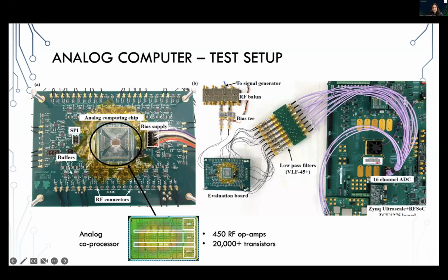And we are using an external signal generator or external supply. We can provide an input signal to this analog chip, and it then produces analog outputs. Those outputs are converted using analog to digital converters into the digital domain for comparison and results post-processing. That's a different part. I wanted to show you this figure because it's an embedded system that we use to test the chip.